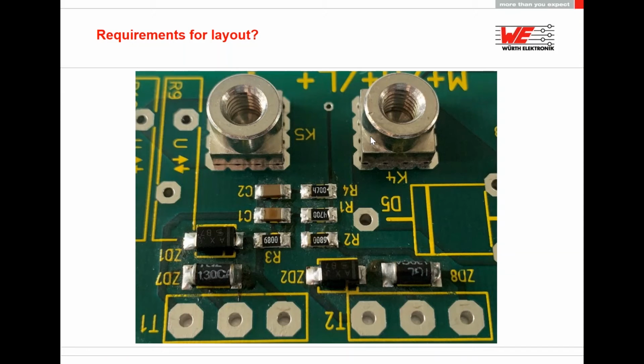Yes, and that's it. Maybe for high voltage applications, you need to keep the creepage and clearance distance according to your voltage. If you have higher voltage, you need bigger distance. If you have lower voltage, you need less distance, because the parts are non-insulated. So you manage it only through the distance to other components, or if you have plus and minus here, then you just generate it by distance.